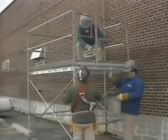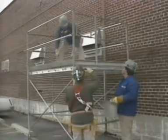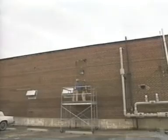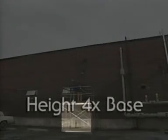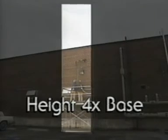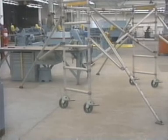While the erection and use guidelines for a mobile scaffold are similar to those for a stationary scaffold, there are specific practices related to its rolling base. To prevent tipping, the maximum work height of a mobile scaffold must not be more than 4 times the shortest distance between any two of its casters. If for any reason this condition of use cannot be met, outrigger frames should be added to enlarge and stabilize the base.